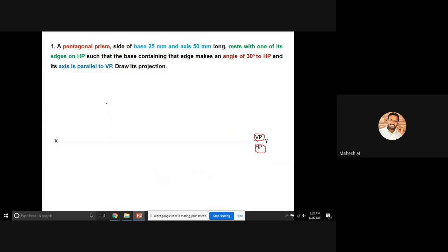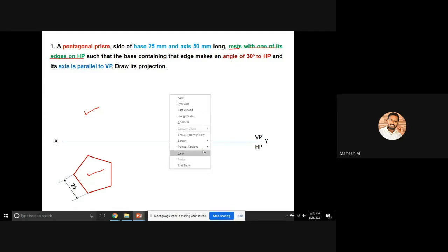Okay. So if you're creating a plane like this, you have to name each and every corner with a letter and also a number. So this one is called the top view. If it is a top view, what is the procedure? The top surface is named as A, B, C, D, E, and the bottom surface is named as 1, 2, 3, 4, 5. Then what is the name of this point? The left side corner. What is the name of this left side corner?